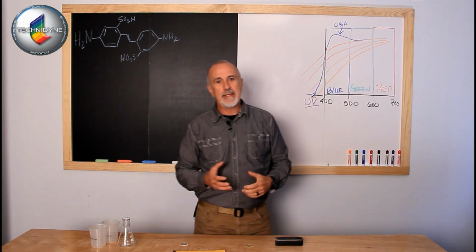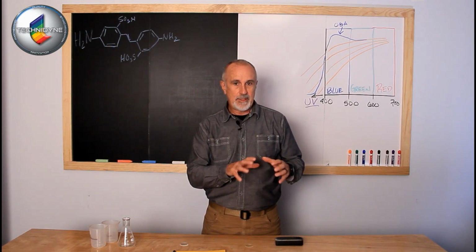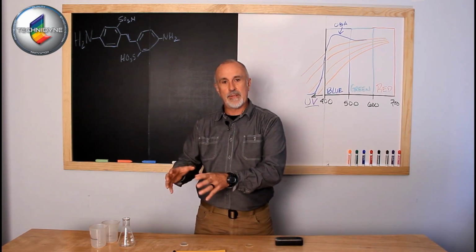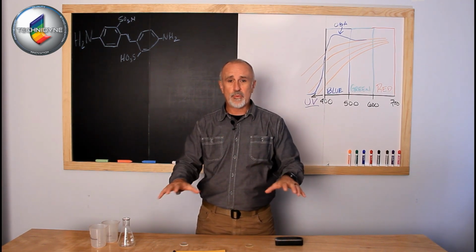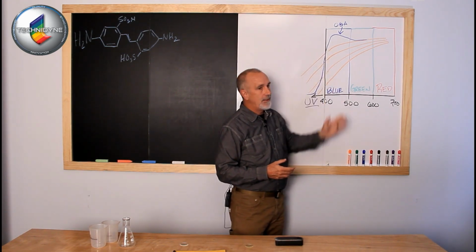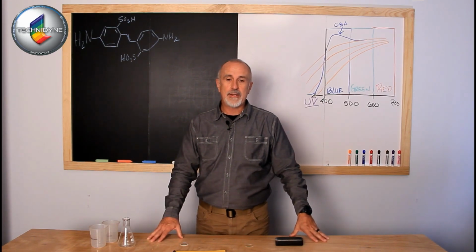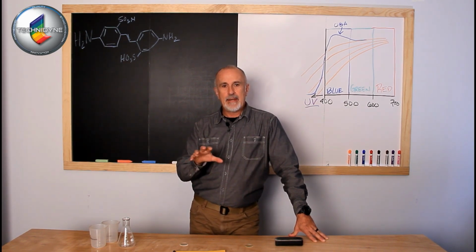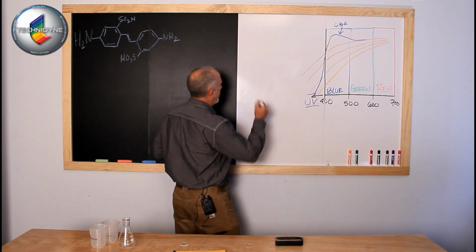Once we introduced the optical brightener into the process, we then took that instrument that was developed to do either TAPPI or ISO, and we applied that instrument to that process, even though now it's measuring something that the original instruments weren't designed to do. Fortunately, because we're still talking about the blue region of the spectrum, a TAPPI instrument or an ISO instrument still does a very effective job of managing that. So when we measure brightness in the industry today, that is done under what's called, I'll write this up here,